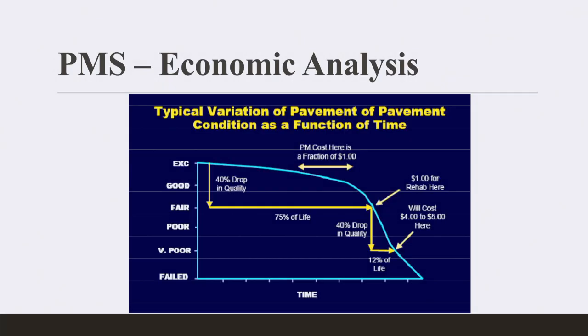Again, I cannot overemphasize how important this is, but here what I wanted to show is at 75, which is fair condition, you still see not too bad of deterioration. Once you pass this, see what the slope is doing, you'll probably accrue a 50 points drop on your PCI or PCR in like 4 or 5 years.